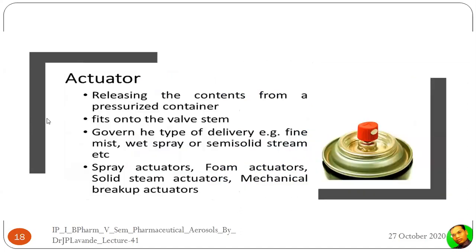Now this is the actuator, as I told you, right? It is responsible for releasing the content from a pressurized container. It fits onto the valve stem and it governs the type of delivery: fine mist, wet spray, or semi-solid stream, etc. The spray actuators, foam actuators, solid stream actuators, and mechanical breakup actuators. All these are the different types of actuators. And it is the actuator which governs upon actuation the kind of spray that comes out.